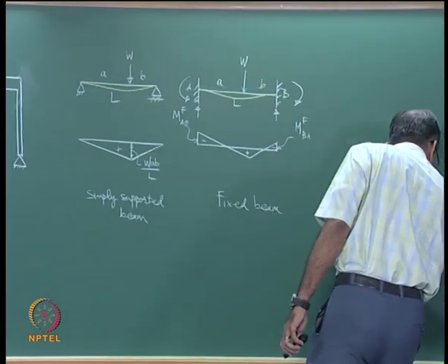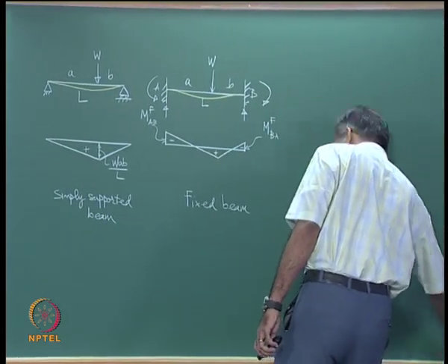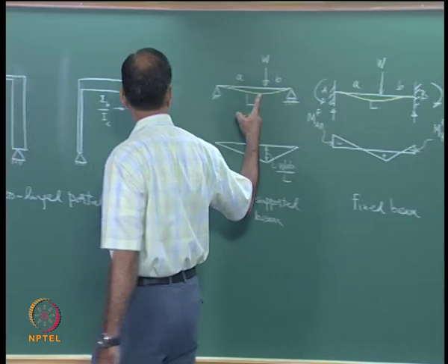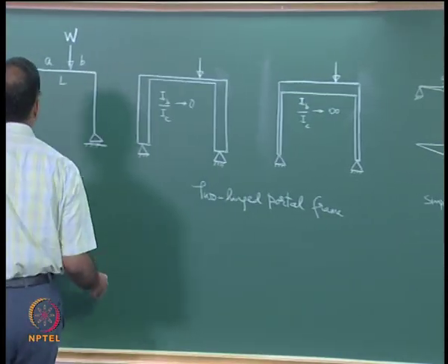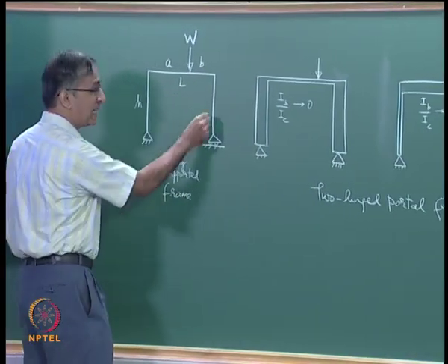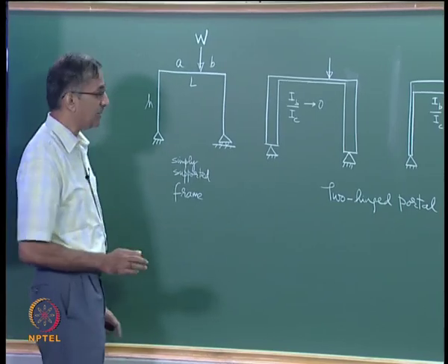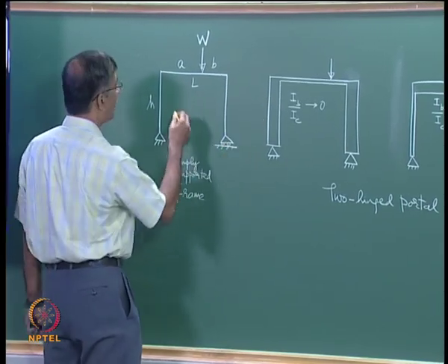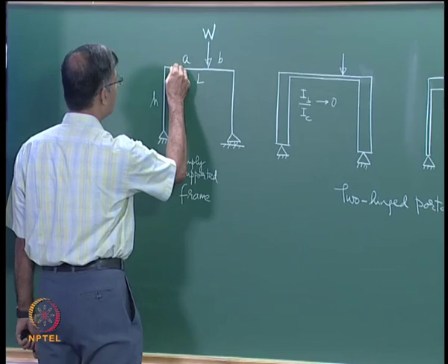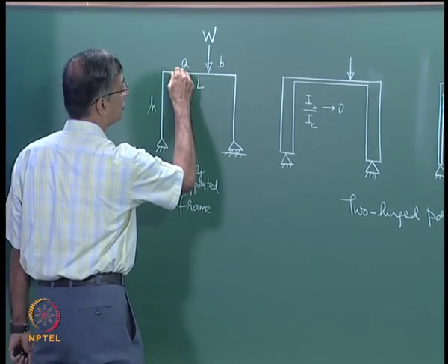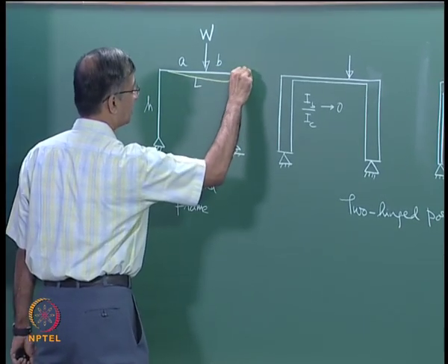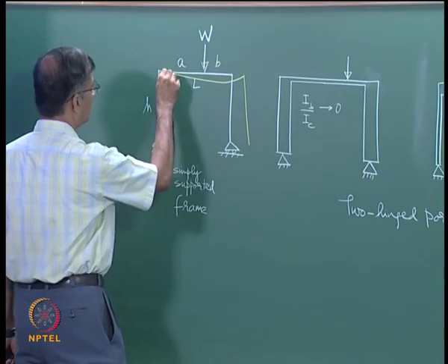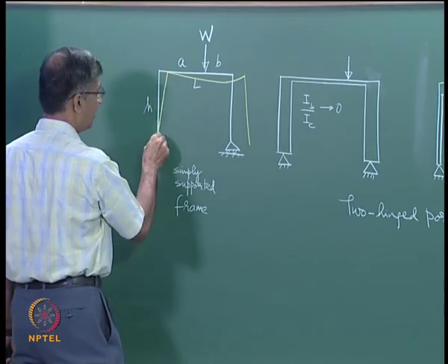If you look at the bending moment diagram, it will be as shown here, and these legs will remain straight. So you have to basically copy that diagram, but it will sway, and so it is going to probably look like this, right.